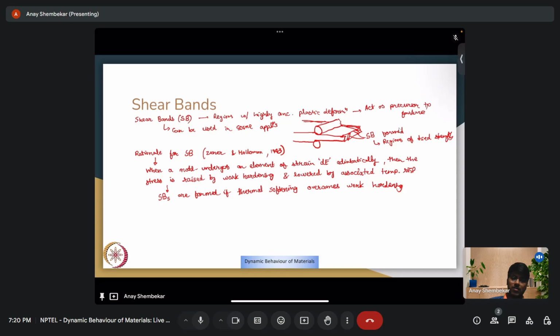If the deformation rate is high, then instead of the process being isothermal, where any heat generated spreads out and the material comes back to ambient temperature, the process slowly shifts from isothermal to adiabatic, thermodynamically speaking, depending on the applied rate of deformation.